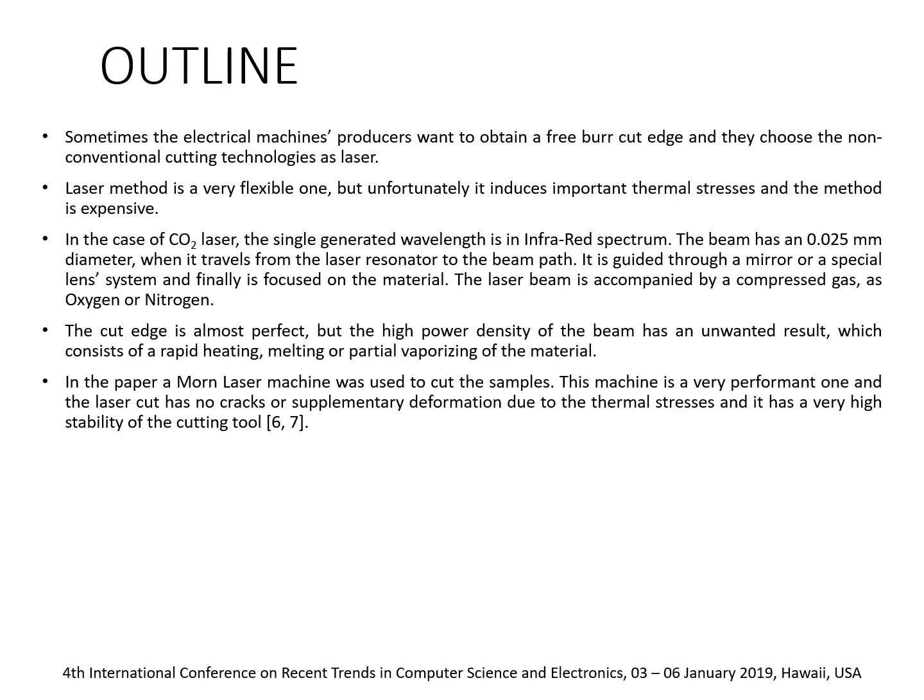Sometimes the electrical machine producer wants to obtain a burr-free cut edge and chooses a non-conventional cutting technology such as laser. The laser method is very flexible, but unfortunately it induces important thermal stresses and the method is expensive. In the case of a CO2 laser, the single generated wavelength is in the infrared spectrum.